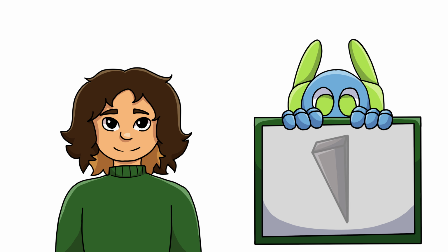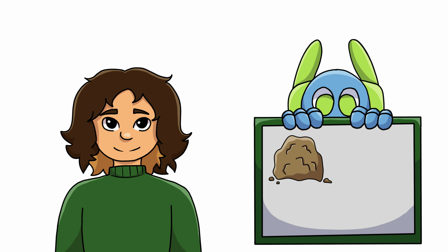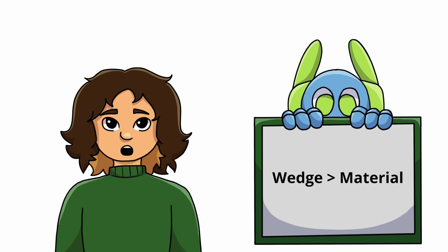It's important to choose the right wedge when you're cutting material. For example, it's good to pay attention to the materials. Some larger rocks need a sharper and metallic wedge to cut, while a softer object can be cut with a softer material. It's important that the material you're using for the wedge is tougher than the material you're cutting though. Otherwise it won't cut, or it may wear out too fast.